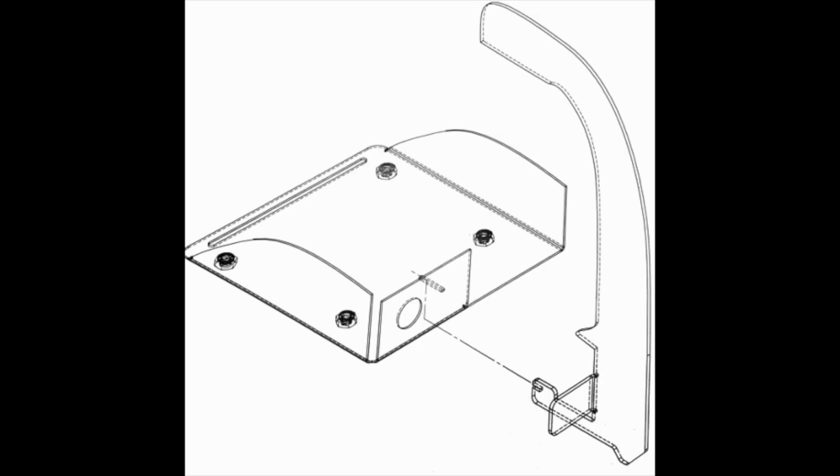This is an example of an isometric drawing, and it contains the parts of the chassis and the upright piece of the maglev device. The isometric drawing is drawn in somewhat of a perspective form, except lines that are parallel on the horizontal plane are parallel as shown in the drawing, and not drawn in perspective or off angle. In isometric drawings, it's common to see geometric features compressed to fill the plane space. For example, some of the circles appear as ellipses, or some of the radii appear stretched or compressed in order to match isometric projection standards.